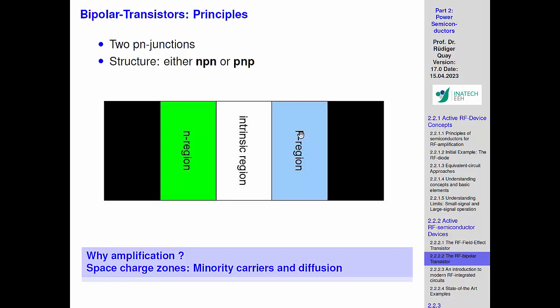What helps is to know something which you already know, which is that there is a second principle in these transistors: the flow of current is not only based on fields, as with the field effect transistors, because there we take a field and modulate a carrier density of one type, and that actually changes a current flow. But you remember there's a relatively strong effect related to diffusion. So these diffusion forces are relatively strong.